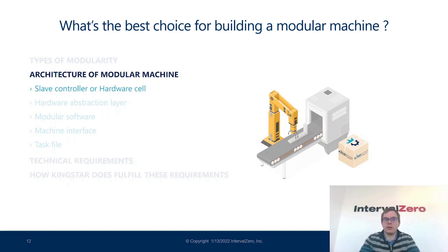It only directly connects to a field bus inside the machine, and the main controller of the machine will connect and control it directly. So this is, for example, let's say in PCB, to flip a board. If you need to flip the board, it could be in packaging, a module to do some labeling, to do some pushing, to do some sorting. So this doesn't need a controller, it uses the main controller of the machine.